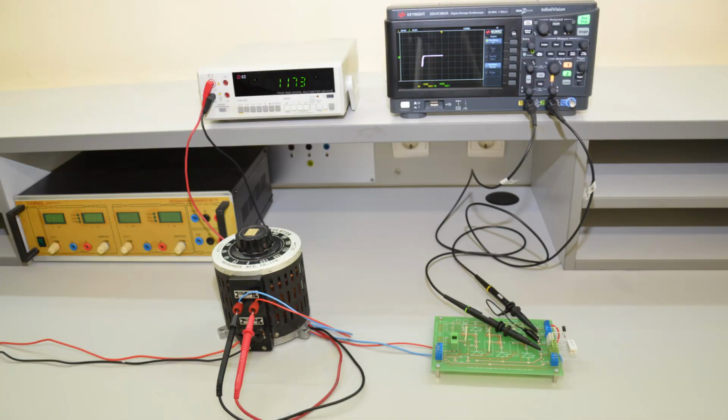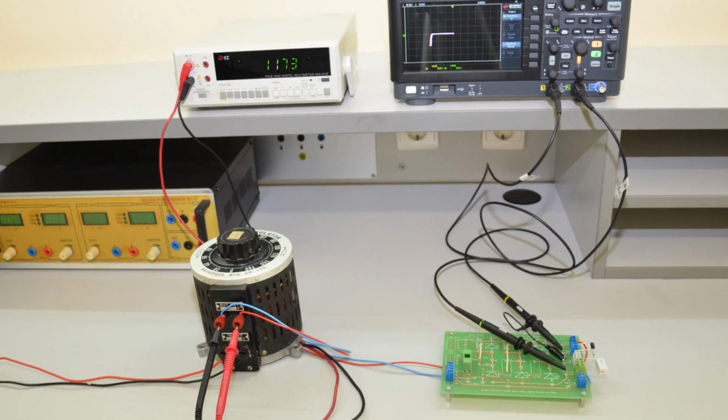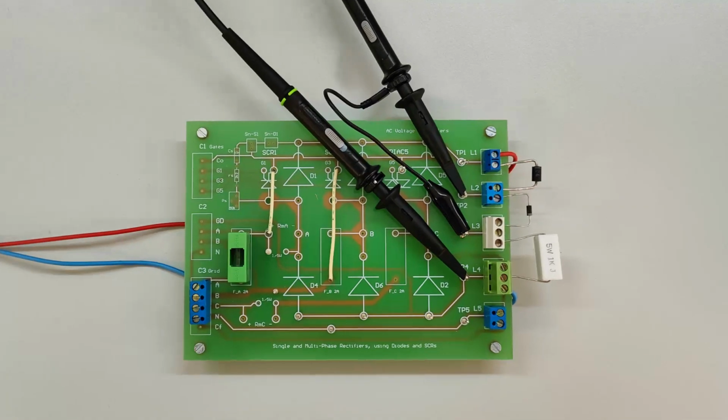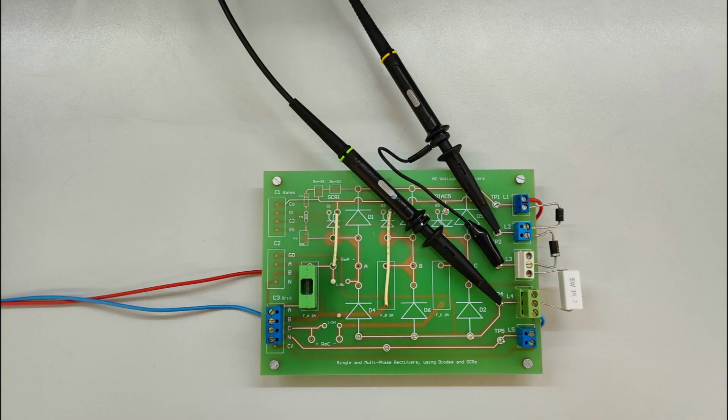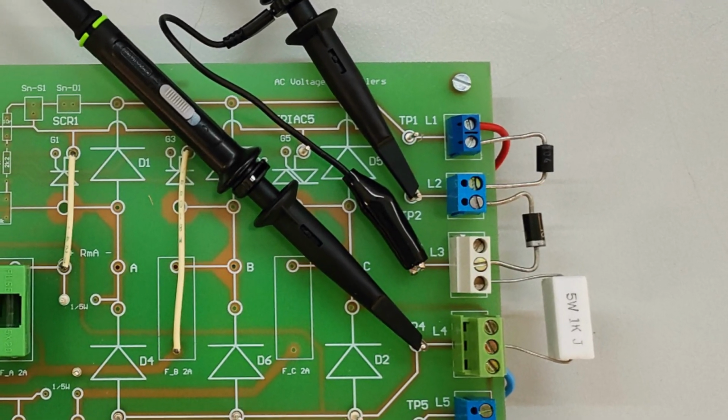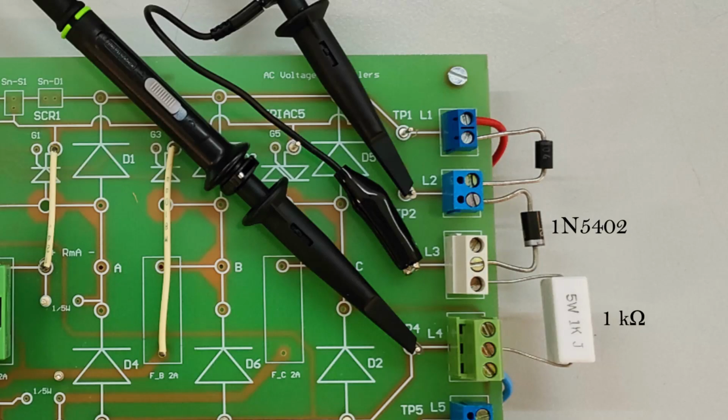The reverse bias section of the characteristic curve, beyond the breakdown voltage, is the most surprising. The diode is usually destroyed when the supply voltage exceeds the breakdown value. The resistor is chosen to be 1 kilo ohm for all diodes.